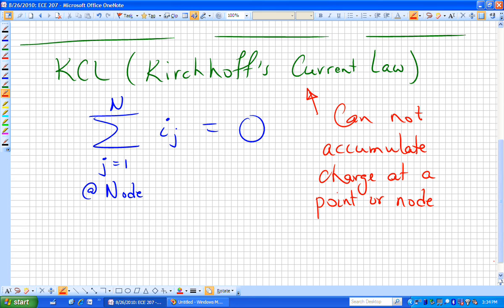Meaning if I have just a wire from this point here, A, so if you're listening to this, you'll have to use your imagination. I'm now walking 10 steps over, and here's another point B, and if that's an electrical connection with just a bare wire, that's the same node, and it would be what we would call the same electrical point. It's physically not the same point, obviously, but electrically it is. And that's what we mean by an electrical point or a node.